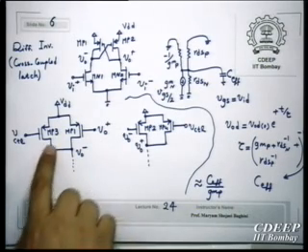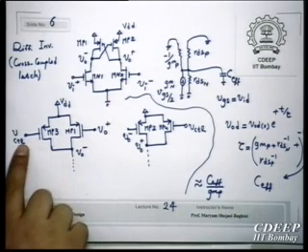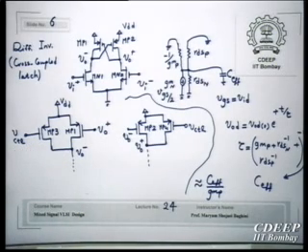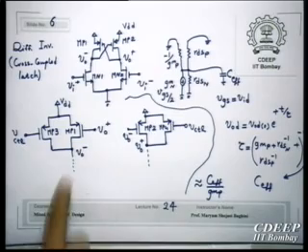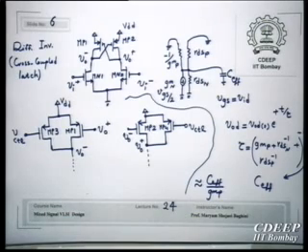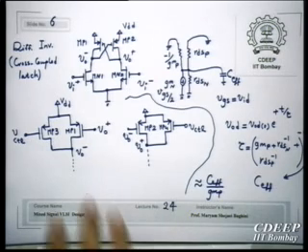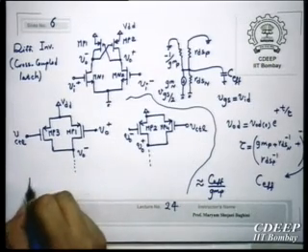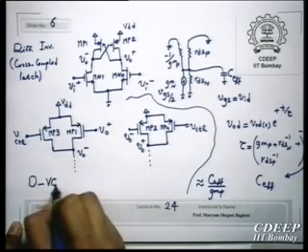If it is almost a resistor and I am changing the value of the resistor with VCTL, this node can reach VDD. When this current is off, this resistor also will have zero drop, therefore I can bring it to VDD. So this is just one simple way of making a differential delay element. So we call it differential voltage control delay.